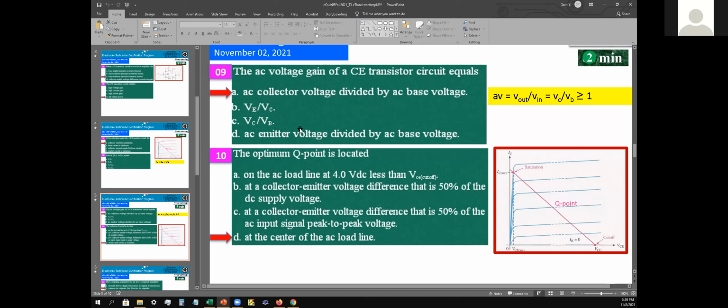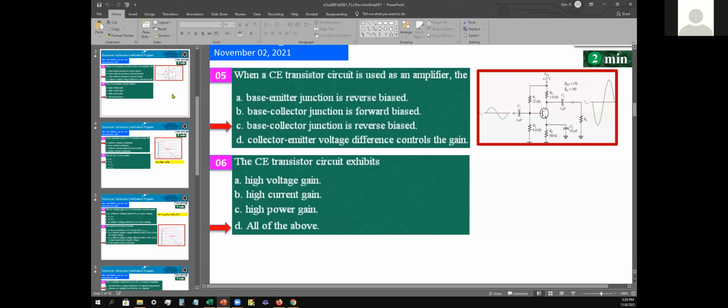What current is flowing first, the AC current or the DC current? Is the DC current considered a conditioner for the circuit before the AC actually starts to take over? DC is mainly just to bias the transistor to make sure the transistor works, and the AC signal passes in and out.